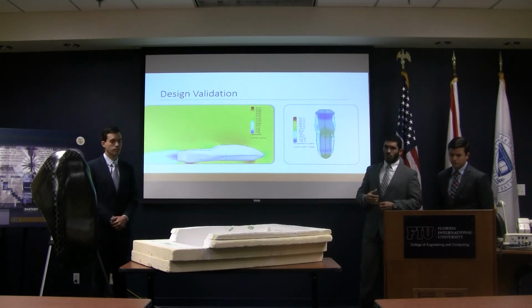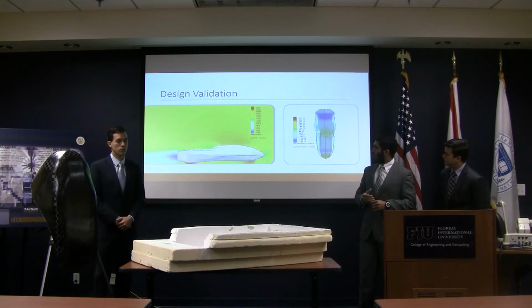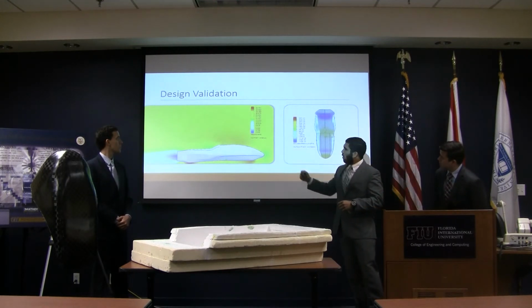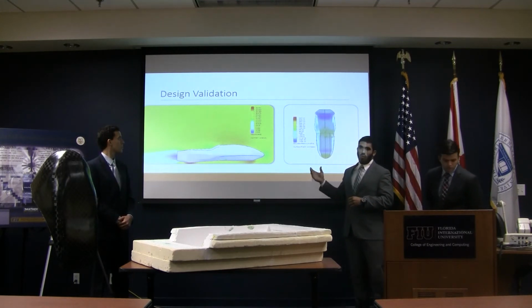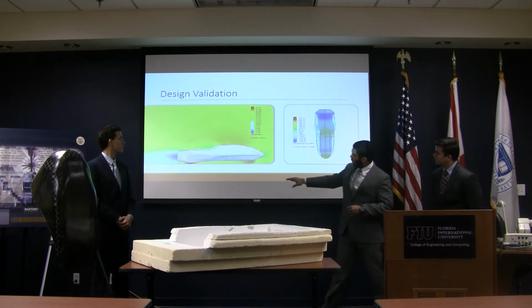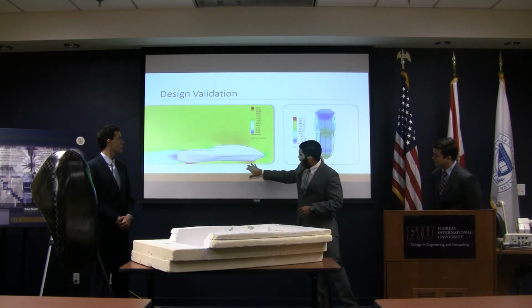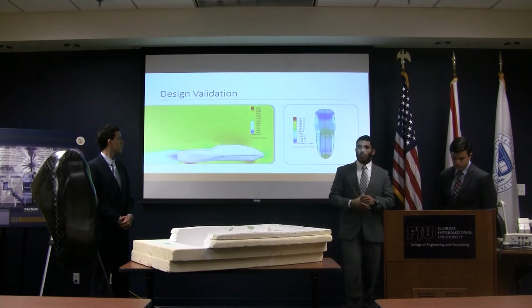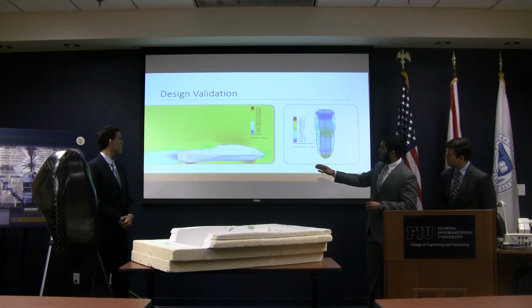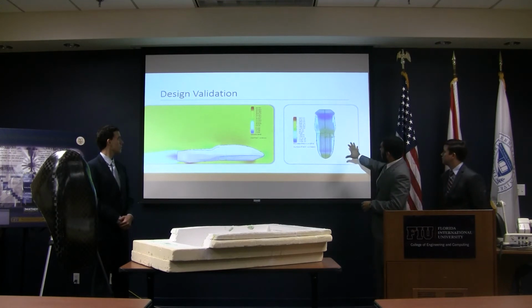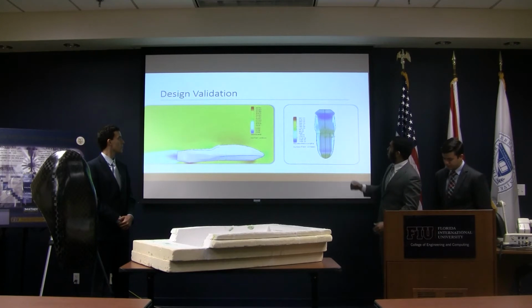We also performed some software flow simulation. As you can see here on your left, we have a plot of air velocity over the car. As you can see here, we're creating two high-speed air areas under the car at the positions where the two axles would be. These two high-speed air areas create two low-pressure zones, visualized here by this relative pressure distribution.